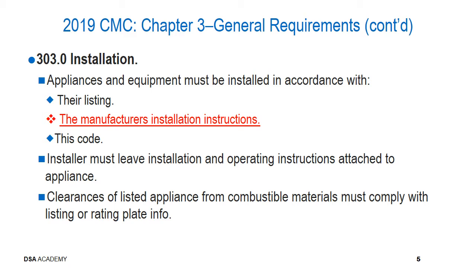And as we've discussed previously, this only makes sense because the manufacturers are the experts for what they've actually designed, and they know best how to install their equipment, their components. Along those same lines, it's critical that the installer leaves the O&M manuals, or the installation and operating instructions, sometimes called the operation and maintenance manuals, attached to the appliance.